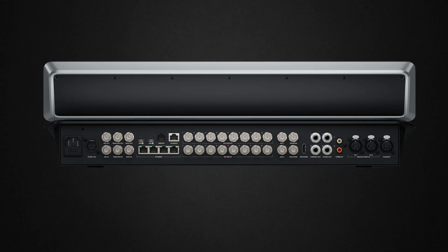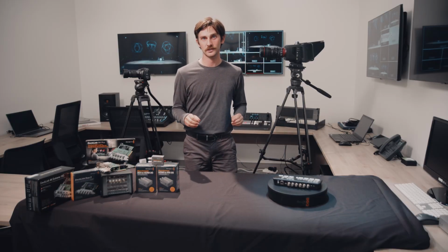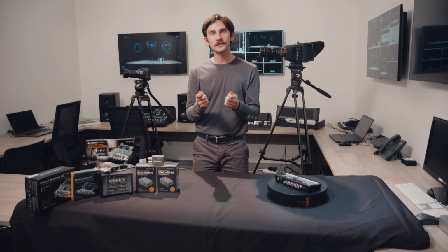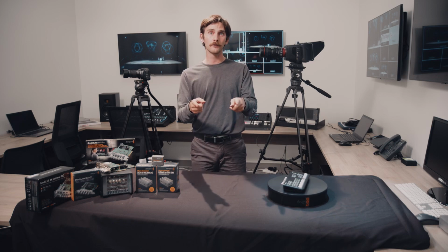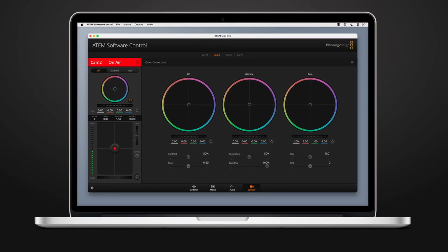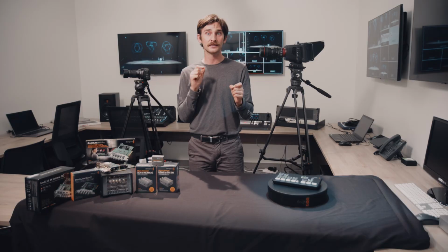Except for the difference in resolution, the television studio models all offer 8 SDI inputs and 12 outputs, 10 aux, and a dedicated multi-view and program feed. You may be wondering why you need quite so many outputs, even more than you have inputs. The reason is that there is some information you want to be able to send back from your switcher to the cameras. Like I mentioned earlier, color control information for your compatible Blackmagic camera can make each of your cameras provide a consistent image, and a program feed back to your camera operator lets them see the graphics layering or the angles of the other camera operators.